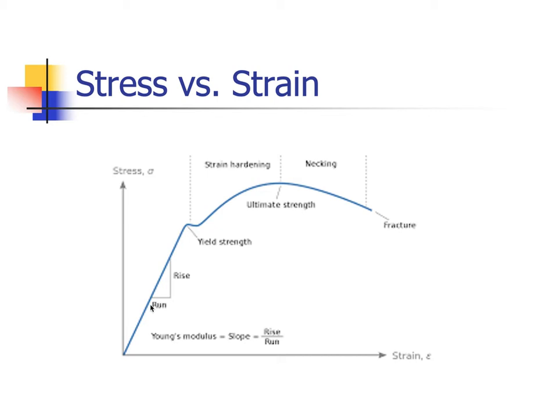Okay, so what happens is we load this piece of material. Now this is what happens in steel. We get this little bump here. And this is due to a phenomenon. It has to do with other atoms, like oxygen and things like that, being stuck between the atoms. Once the metal gets to a certain yield point, it drops down a little bit, and then it starts to work harden and goes up. This is just a phenomenon that happens in steel and maybe a couple other alloys or elements. Okay, so we get strain hardening or cold working or work hardening, all the same thing.